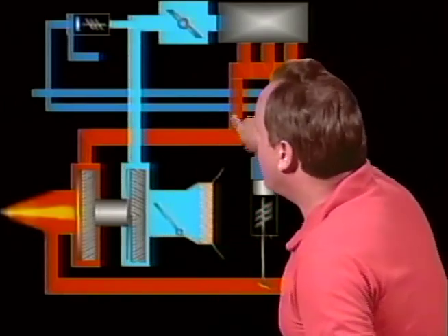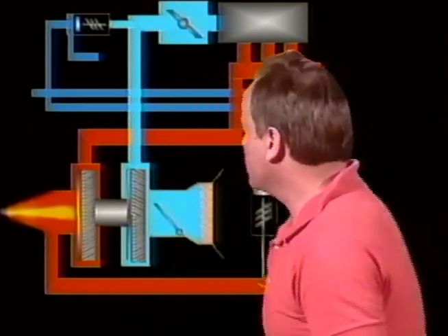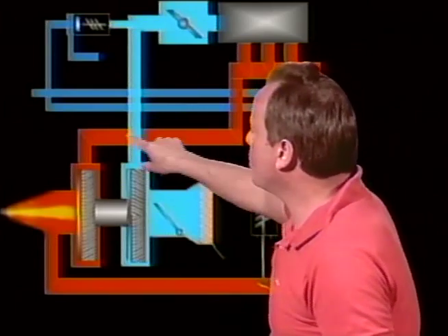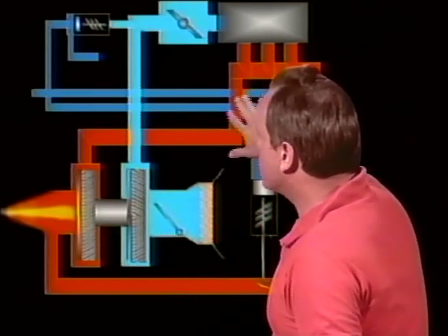But they are going to ask you some more questions about turbochargers. One of the questions they're going to ask you is, how is a turbocharger driven? What's the power for a turbocharger? And by the way, they call these turbo superchargers or sometimes externally driven superchargers. And so a turbocharger is called an externally driven supercharger or a turbo supercharger on the FAA written exam. They're the same thing. A supercharger is called an internally driven supercharger.